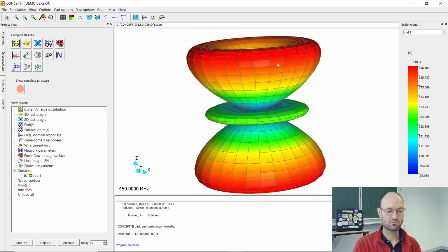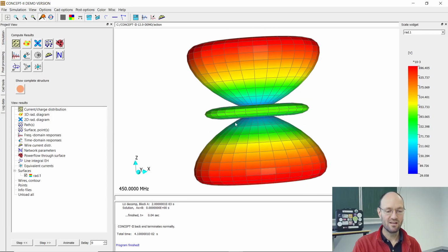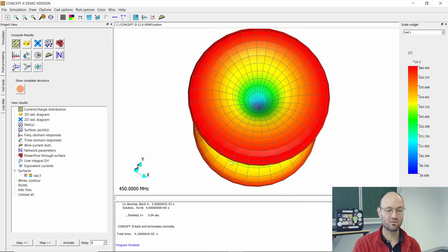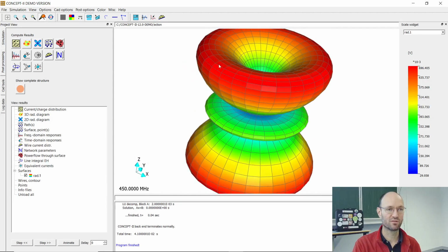So there can be positive interference and negative interference, and that's why you get something that looks like this. There is some very compressed donut in the center, but in this case two much larger loops that are radiating towards the top and towards the bottom. There's of course still nothing radiating straight along the wire axis, and there will never be.